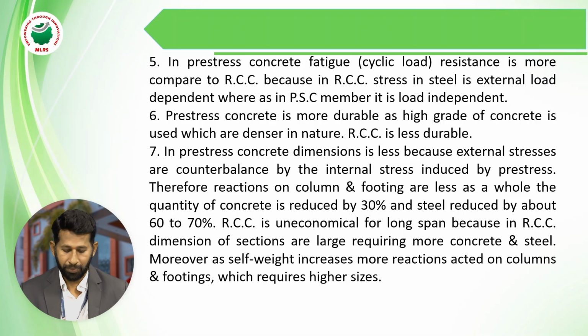less durable. In prestressed concrete, dimensions are less because external stresses are counteracted by the internal stresses induced by prestressing. Generally there is a concrete reduction of about 30% and steel reduction of about 60 to 70%. RCC is uneconomical for long spans because the sections are large, requiring more concrete and steel.